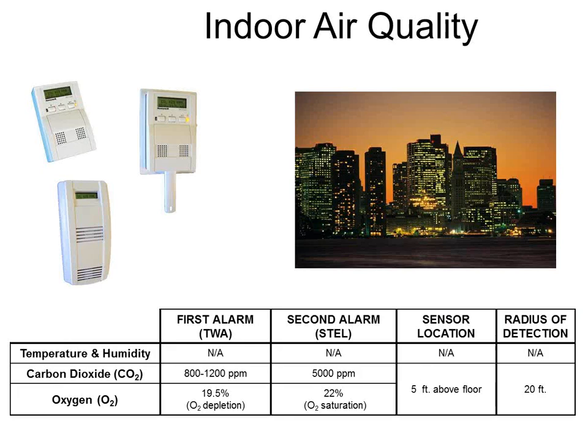Actually, speaking of that, Jonathan writes in, is DCV typically controlled by average return air CO2 for multi-zone systems? Definitely not. You cannot do it that way for sure. If you have a zoning system, you absolutely cannot put the sensor in the return duct.